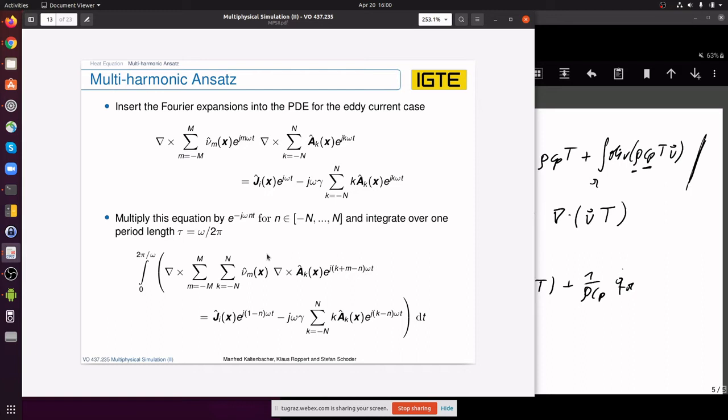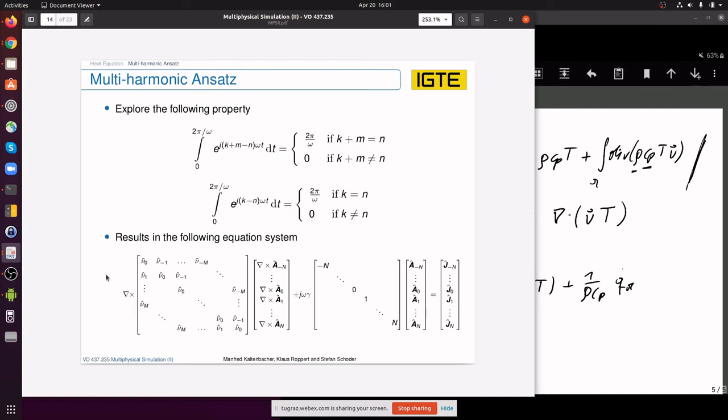If we then solve for the Joule losses, the J in E, we have a steady state Joule loss that we can prescribe into a transient thermal problem or a steady state thermal problem, so that this does not matter afterwards, since we're using period averaged quantities here in the magnetic problem. Okay, then we can